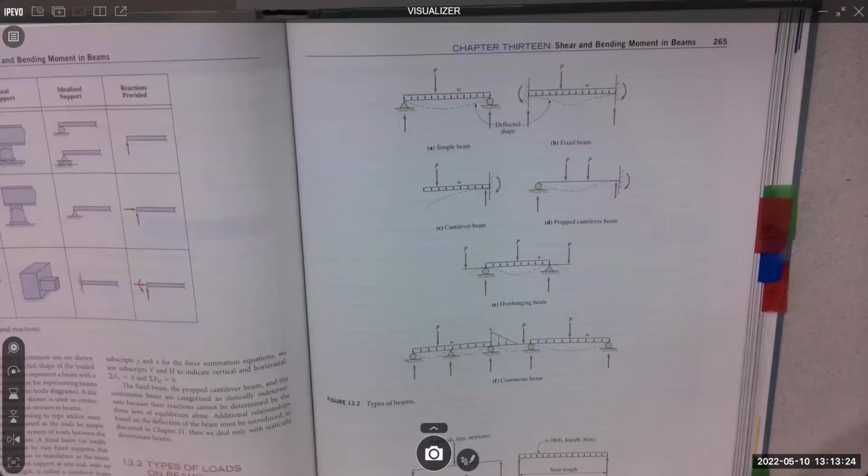So the way we do that is what you described: it's the area of the load curve. You've got to calculate the area of the load curve, and then you've got to find the geometric center of that area. If it's complicated, if it's got a bunch of geometry to it, then just break the geometry down and do those independently.